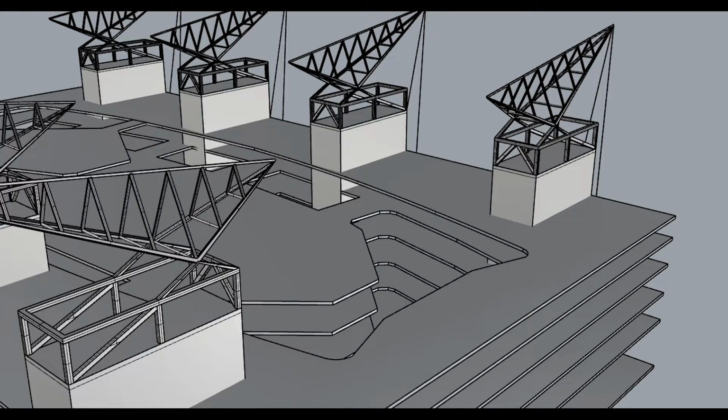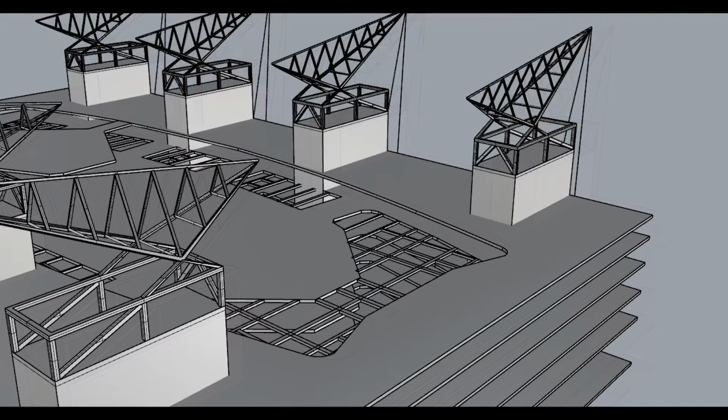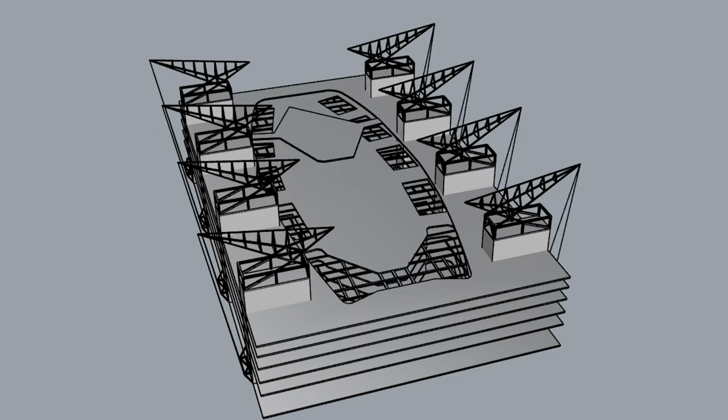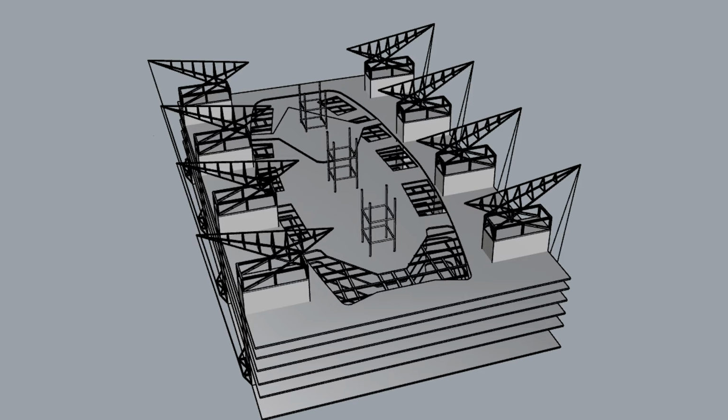First, as you see in the case of the 5th floor, temporary steel frames were installed in an empty space between the slabs for the installation of the bands. And the 6th floor was not built perfectly at that time, so the temporary structures were installed where the actual structures should be built. Then they merged with them after construction.